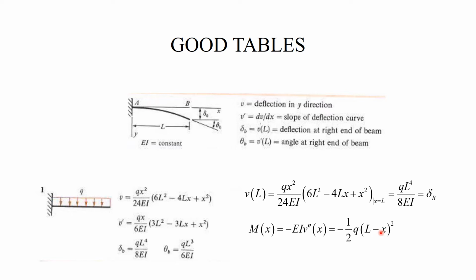And at x equal to L, it is 0, and indeed that's true because there are no couples applied at the tip. Now, I can do pretty much the same with the shear force. Again, get the expected linear function, which gives me QL, or the force up, at the left end, and 0 force at the right end, and both of them are consistent with equilibrium.